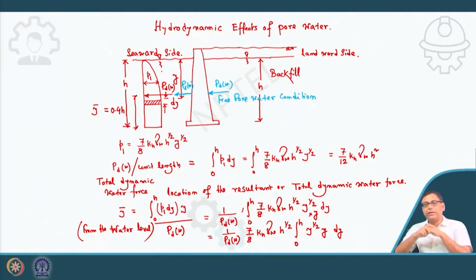Now, there is a question still. We have discussed if this water pressure is very large or high enough or it is small enough. That means the two extreme conditions. Now, what will happen in between, if the water pressure is between that? Again, there are a few recommendations available. Few researchers say don't consider the hydrodynamic force in this situation, it is only if it is free pore water condition, but some have mentioned that you take 70% of that PWD in the backfill side.